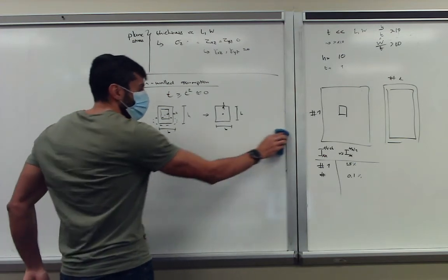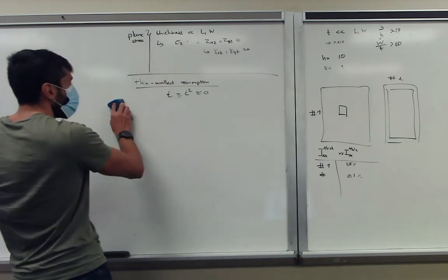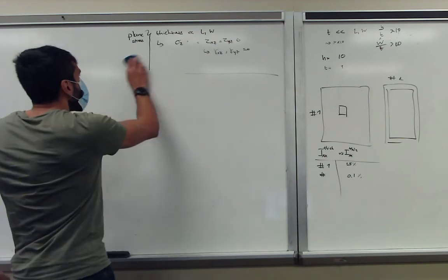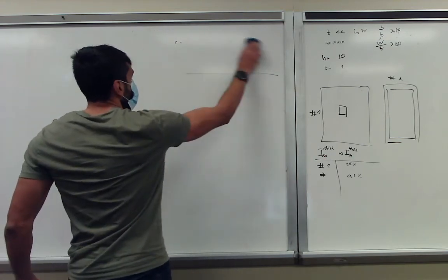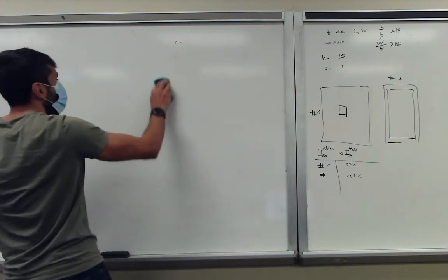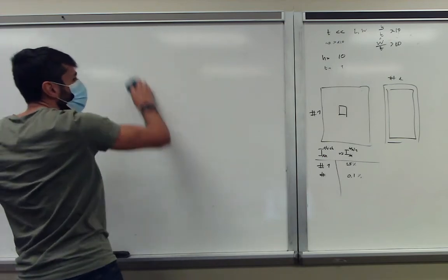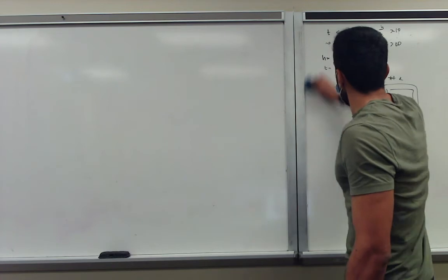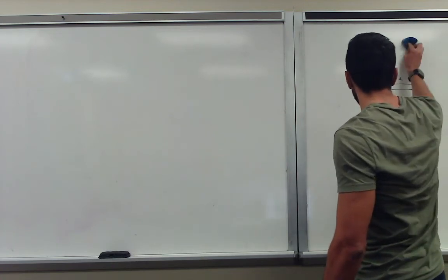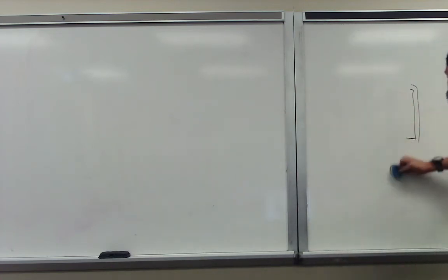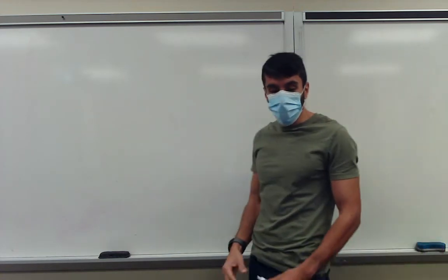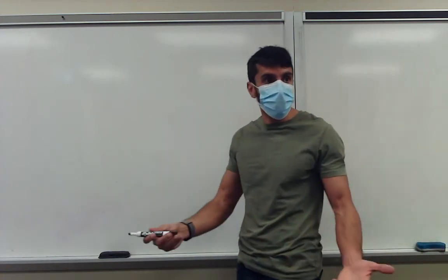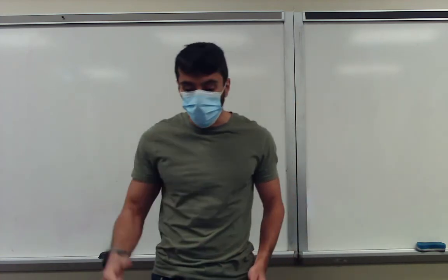You're free to always make assumptions to make your life easier. You just have to make sure that, if it's not mentioned anywhere, you mention yourself that you use a thin wall assumption or a plane stress or plane strain. But often from the problem, for example in stress problems, if it's a 2D stress problem, then you can often assume one of the dimensions is already being ignored.